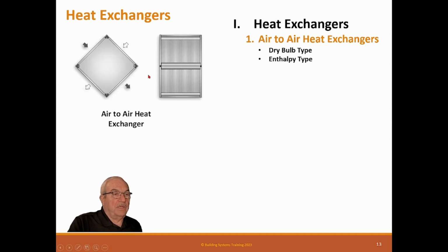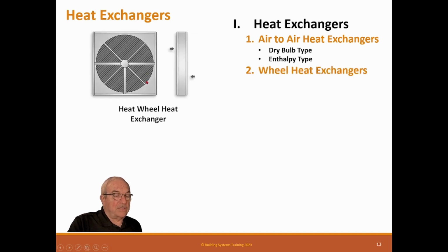The difference between a heat exchanger like this and a heat exchanger like this is the amount of bypass. And the heat wheels come in dry bulb or enthalpy bulb. But what happens is this is the one side and this is one side. So this is probably the exhaust air. This is the outside air coming in. So you can see that they're opposite. This way, so this one goes this way. Well, the only thing that separates these two streams is there's brushes right here and brushes around the wheel.